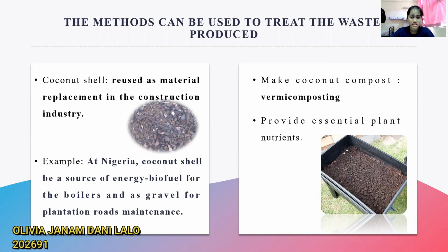According to Kanojia and Jain, a recent study showed that 40% replacement of conventional aggregate with coconut shell could decrease the compressive strength of concrete by about 22%, and to improve this property, reduction of the water to cement ratio was necessary. Shafiq also said that concrete made with coconut shell has higher compressive strength than concrete containing oil palm shell because of the roughness of the coconut shell and its better adhesion with cement flakes.